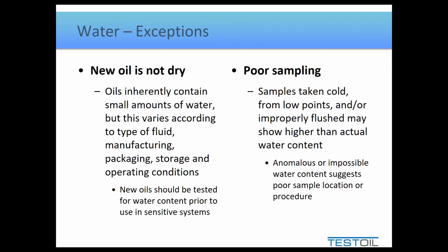So, a couple of the exceptions. We should accept the fact, like we said, new oil is not clean oil. New oil is also not dry oil. All oil tends to have some water content to begin with. So we should appreciate that every time we add new oil, we may be injecting a little bit of extra water, and that under normal operating conditions, that water content may in fact be lower.